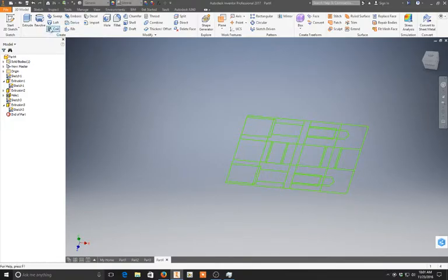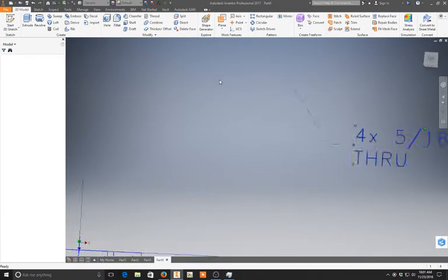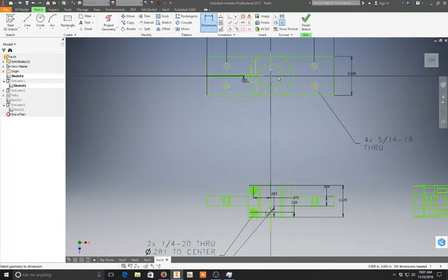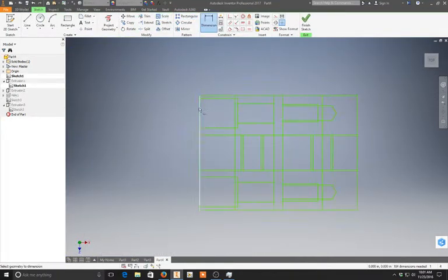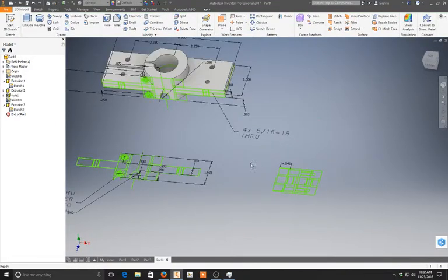So I'm going to edit the sketch. And this is just going to be a reference. Well, I mean, it's going to be a true dimension, but I click here, and that gives us the dimension, which I'm going to change to 0.541. Just for some reason it wasn't there exactly. Okay, so that's going to be our counterbore depth from this outer surface.